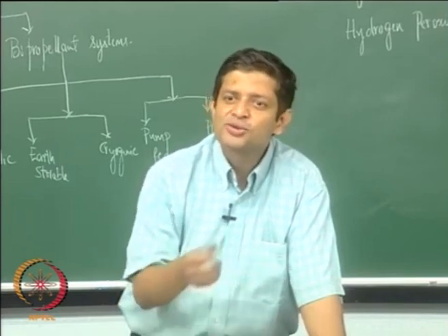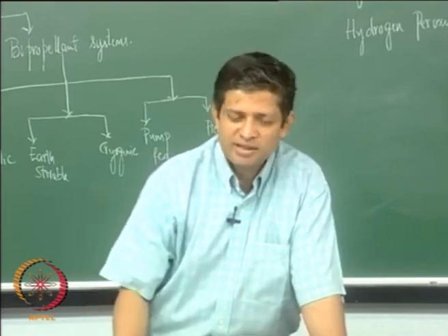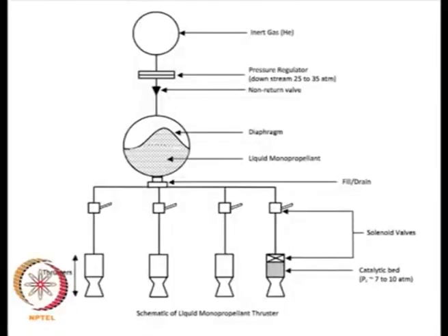So you are not free to choose the best oxidizer and the best fuel, whereas in a liquid rocket motor you have this freedom of choosing the best oxidizer and the best fuel. So therefore you need to have storage and thrust chamber separate. This portion above the thruster is known as the feed system or the storage tanks, and this is the thruster here.